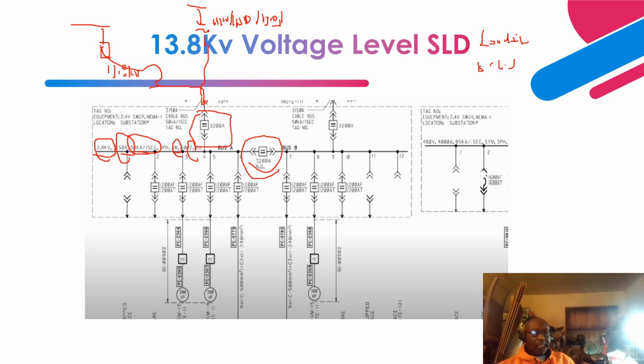Okay, so this is the breaker, as you can see, and I indicated from the legends, the symbols, that this is a withdrawable breaker. You see, they call these the breaker stops. So these are the breaker stops, basically that show you that it's a drawout breaker rated at 3200 amps. So this is the continuous rating of the breaker.